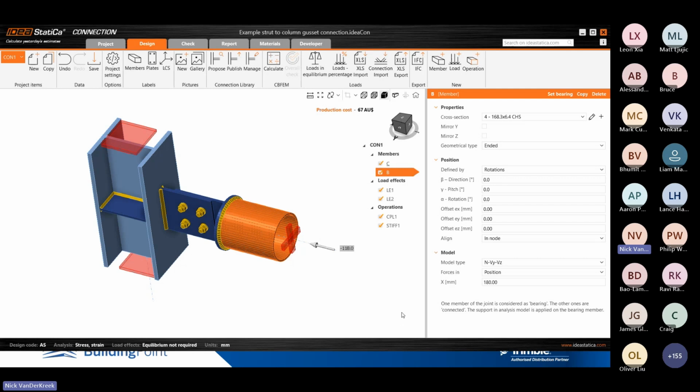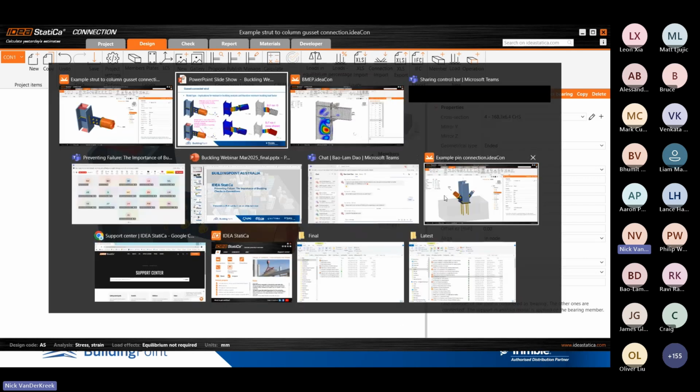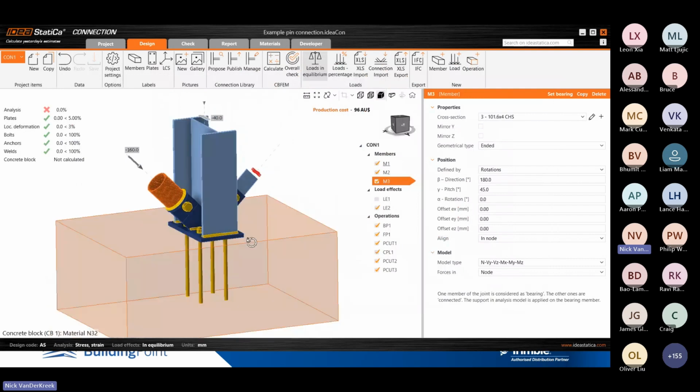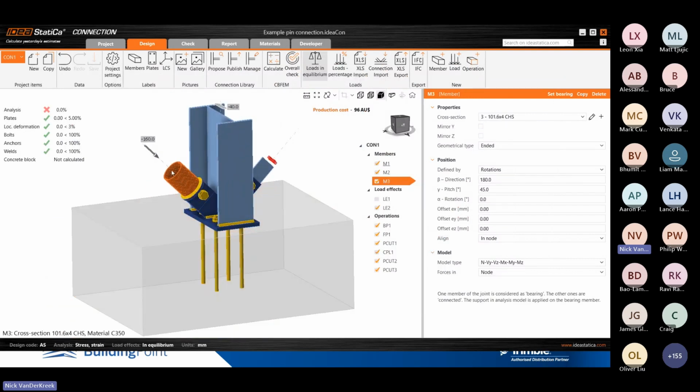And there's another situation like this, I'll go to quickly, which is a single bolt connection like this. And again, this comes up in support a bit. We have the connection all set up, but the analysis iterates down to 0 essentially. Well, it's because there's a rotational instability about this bolt.